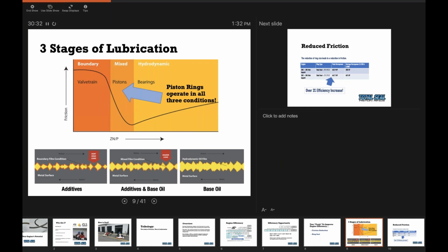But as the piston approaches top dead center, 2 things begin to happen. One, it starts to slow down, but also as it approaches top dead center, cylinder pressure is building. The Stribeck curve is viscosity times speed divided by load. So in the operating environment, at operating temperature of the engine, the viscosity is not going to change. It's a fixed value at that point. Now, obviously, the engine gets hotter or colder, that can change, and you can change that by changing the oil.